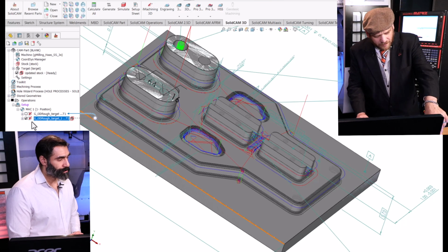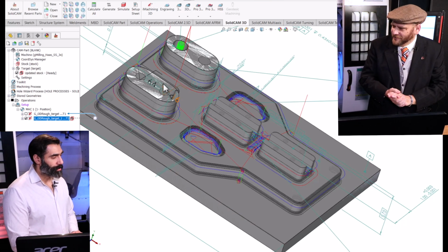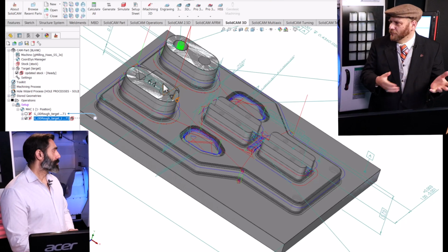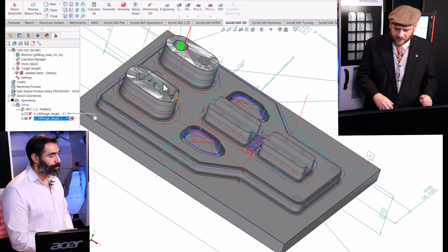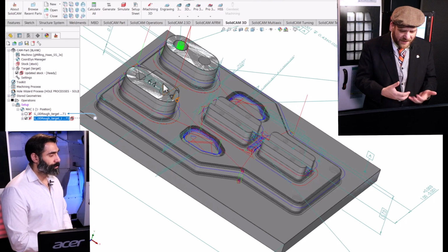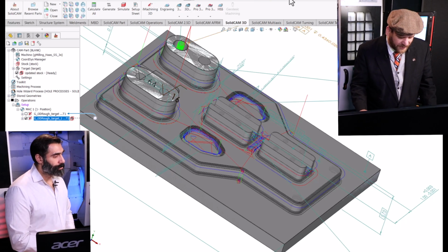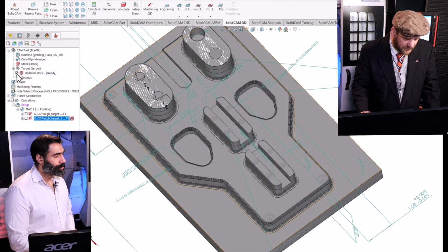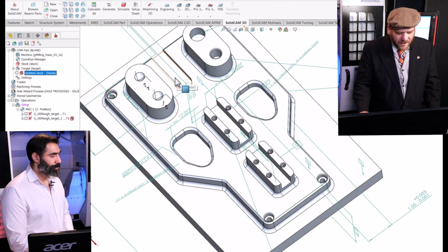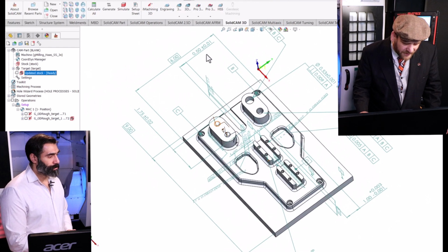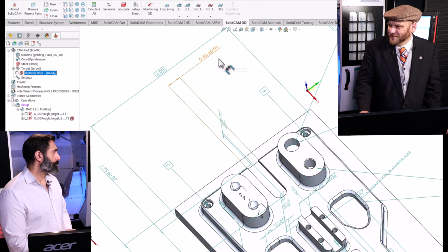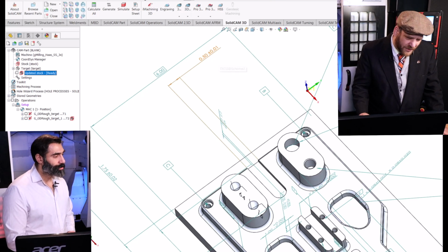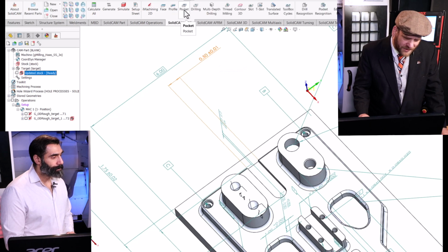And you can see how it went into some of the corners where that 1/2" tool didn't fit. So that really brought most of my part to within size. I'm within 20 thousandths everywhere right now. So now let's start adding on things to finish this model. What I'm going to do first is I have a real simple slot here. And the tolerance on that is ±10. That's really open. I like to start with what's easy. So I'm going to come in here and I'm going to do a pocket operation.